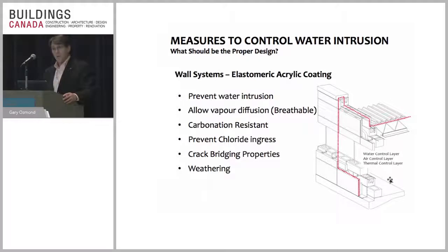With elastomeric coatings, and there's a number on the market, the avenue here is to ensure that you are able to make a continuous connection up and over and around the frames to tie into other materials. Elastomeric coatings prevent water intrusion when applied.